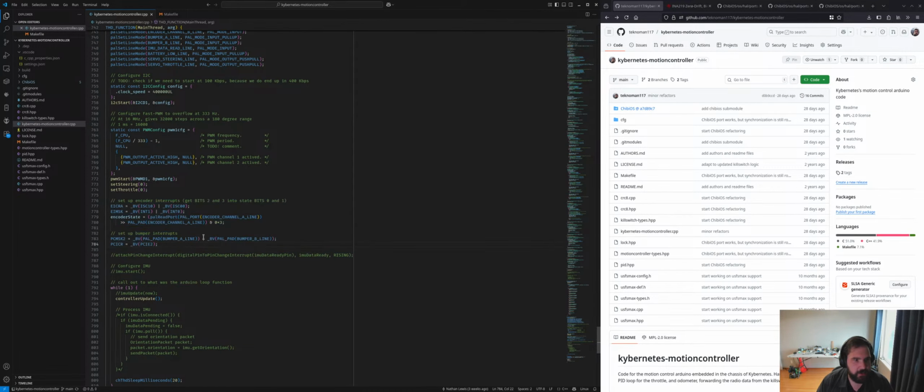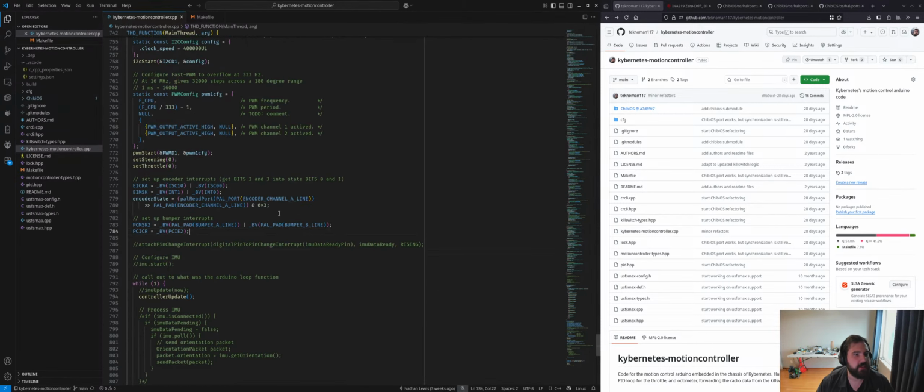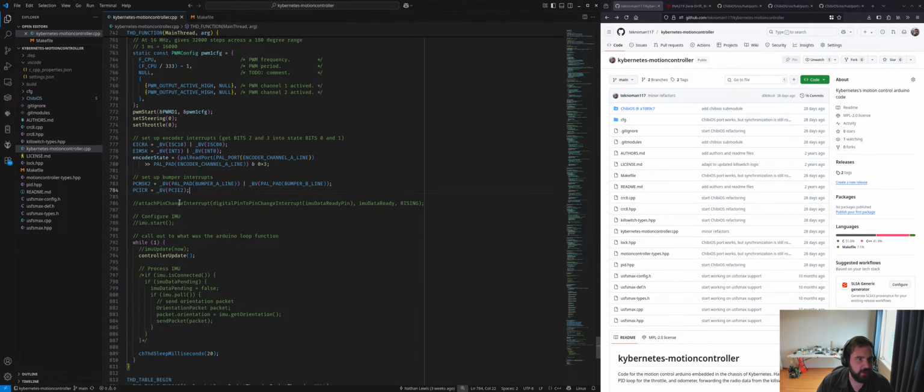Oh, right, I have to zoom in so everyone can see. That's what the register setting here was, with the EICRA and EIMSK external interrupt mask register. That's what all these were: setting up the external interrupts such that we could use them, because again, support's not built in.